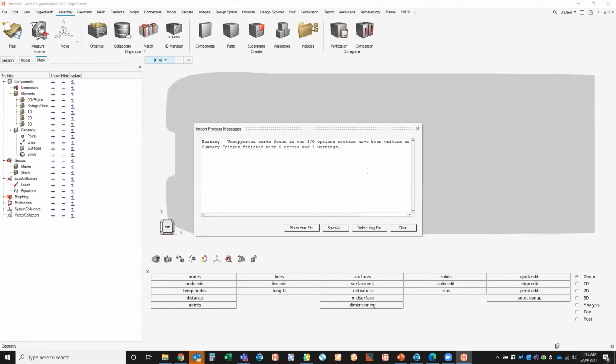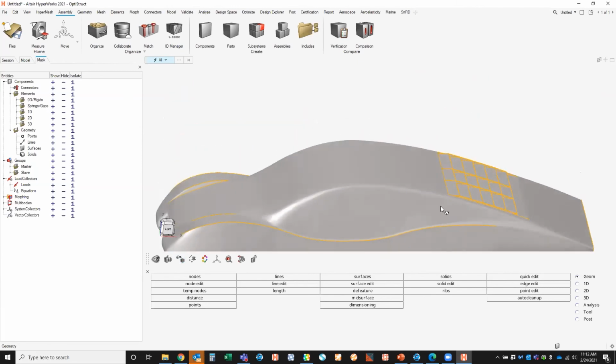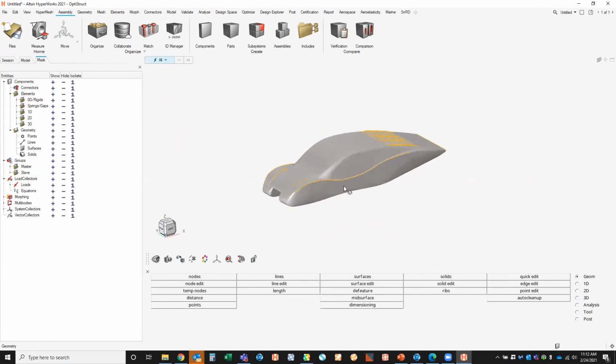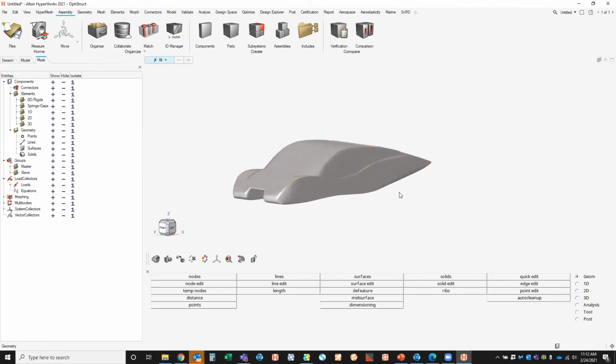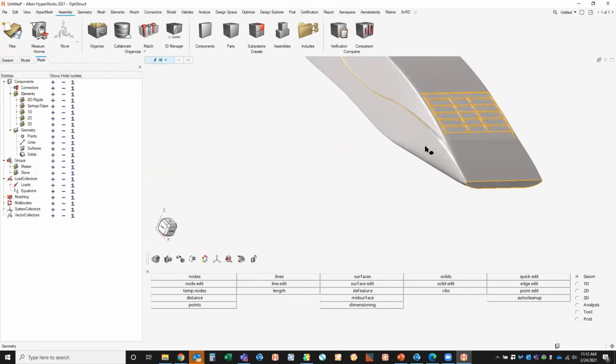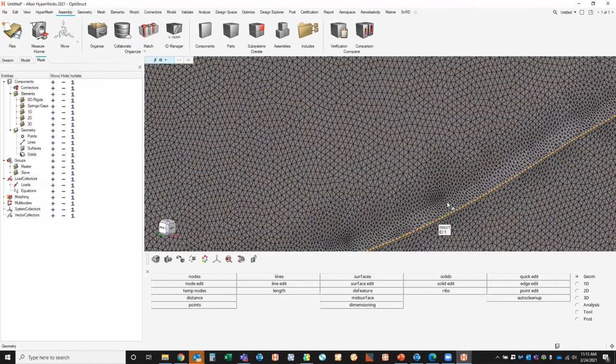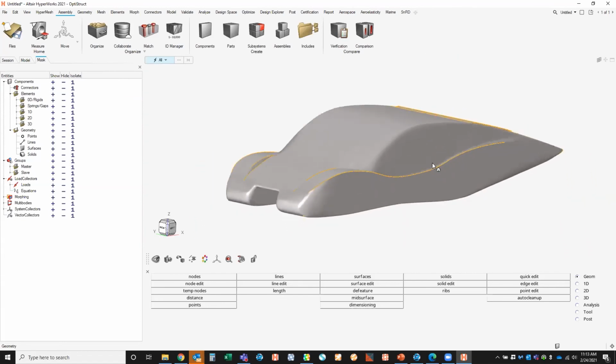So 99% of the time when you get those meshing errors, the problem lies in your setup before you import it into Virtual Wind Tunnel. If you don't model it appropriately or you don't mesh it appropriately, if you have any free edges in your model, that's what's going to cause a lot of these issues. So if I zoom in here at a bird's eye view, we see it's an incredibly fine mesh. I don't see any problems right away.